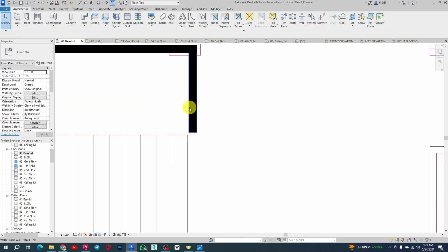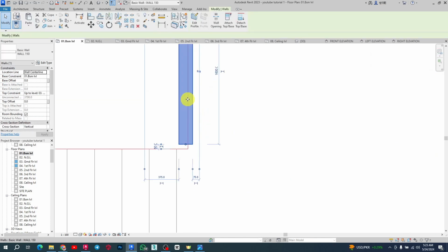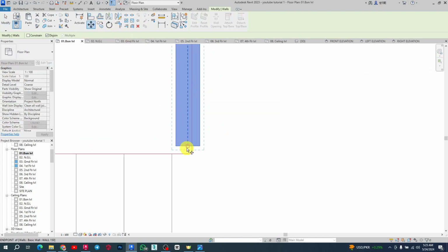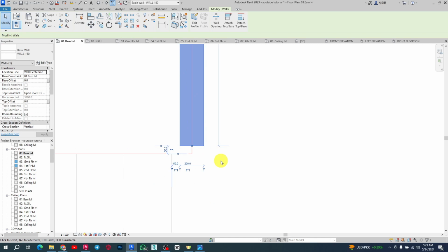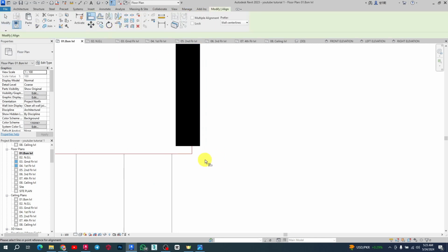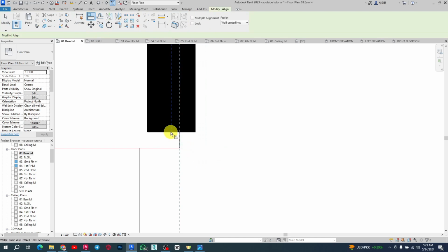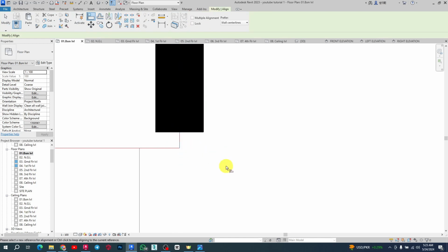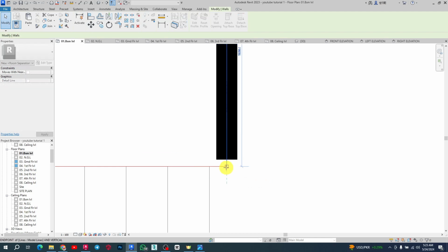And look at this, a mistake that I made, and I want to drag this wall to feature at the center there, right? So I'm going to go here and probably drag from this center point. You see that it's reaching the end point, so I can just drag and drop here. Or if I don't want to go down that route, I can come to my align. I want to align this to the center of this. So you see that's how you can go about it.